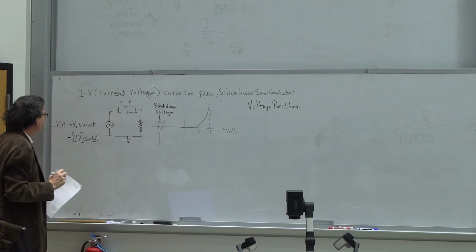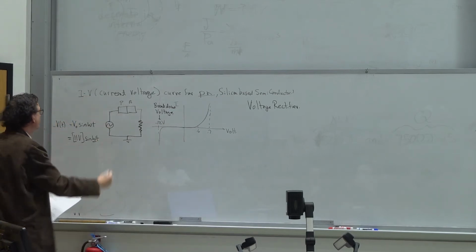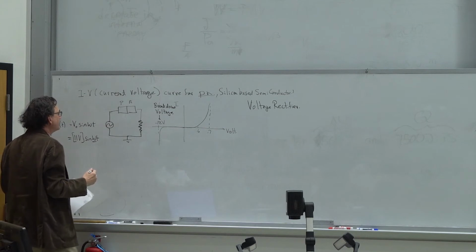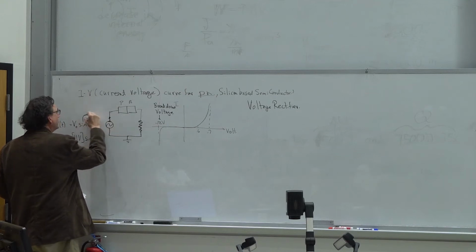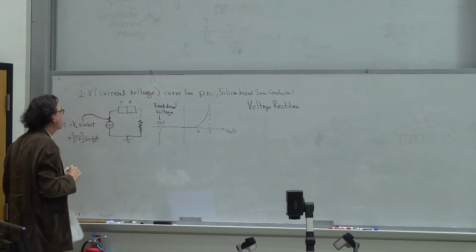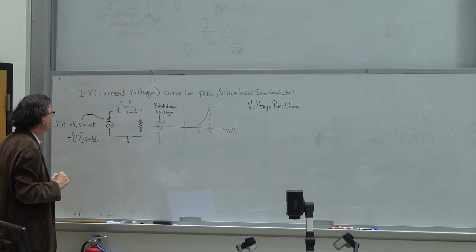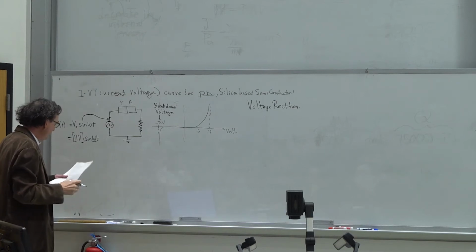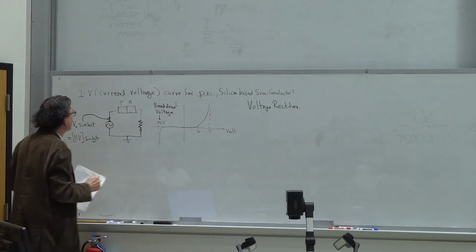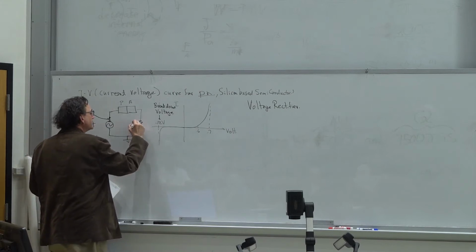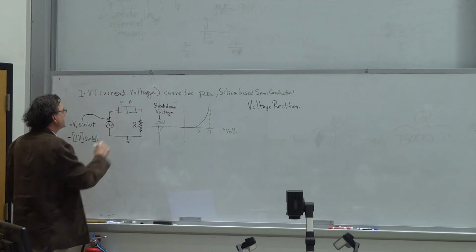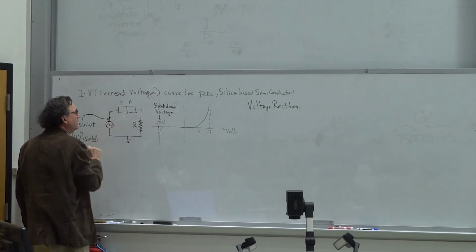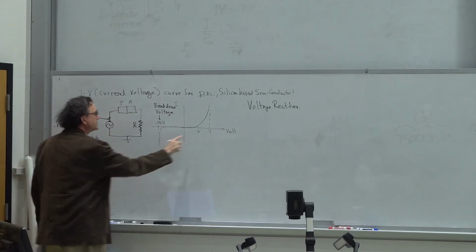So this is going to swing between plus or minus 11 volts on the output side right here. Okay, so what happens when I connect this circuit across a resistor? Well, we know that this thing is only going to conduct when I get above 0.6 volts.